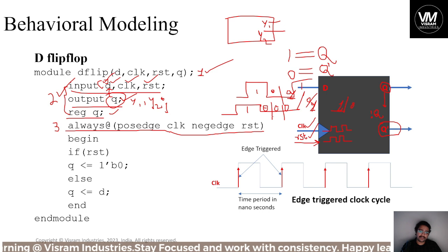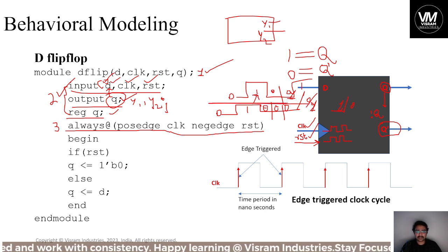If you want to give this kind of data for the D input in the second round of simulation, what will you do? You can't overwrite the data on the same port. Hence we need to reset the data, reset the clock that is going to the D input, and when you reset the entire circuit, again D can take another input.